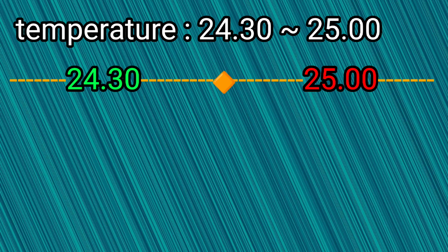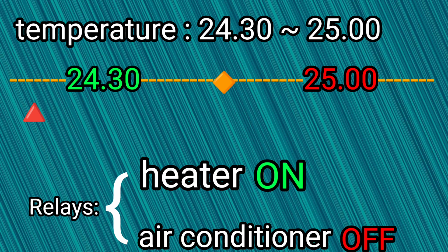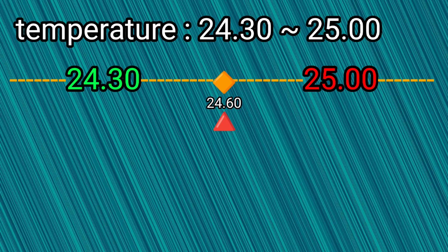The functionality of this program is similar to our previous video on the channel, with the difference that we use the NodeMCU module to create a user interface for entering temperature and humidity range values. We define a temperature range that includes the minimum and maximum values. When the temperature is lower than the minimum, the heater output is activated, and when it reaches the average number, it becomes inactive. The program calculates the average of the minimum and maximum inputs.